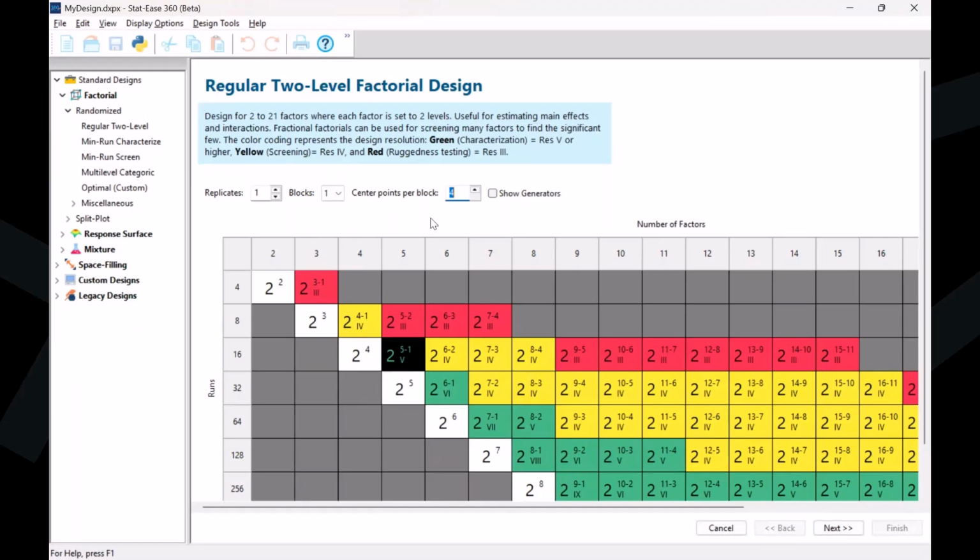Putting center points into the experiment is very helpful, because then basically you're doing an experiment with the standard conditions around which you vary each of the levels high and low. And now I can scale up the agitation, because the chemist will say, keep the stirring magnet running at a certain level. And I just kind of laugh and say, well, I'm going to go to the pilot plant, the semi-works, and eventually a 2,000-gallon reactor. So I'm going to have to kind of recalibrate all these factors, and the 2-level design works beautifully.